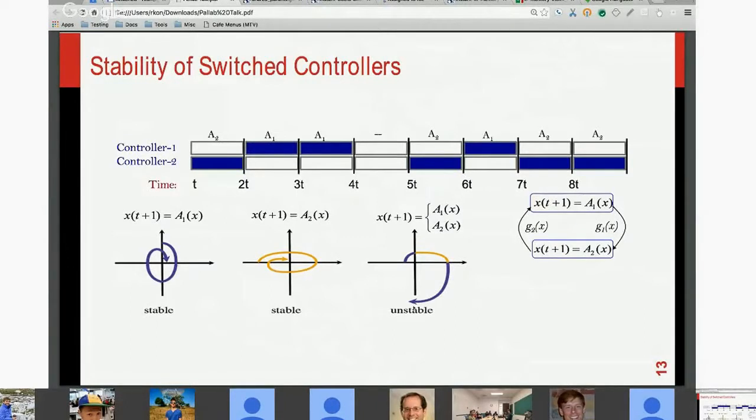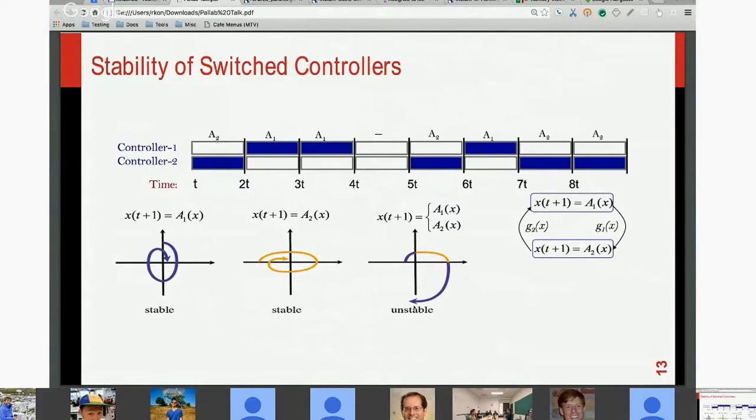There is a nice example which we use when we try to explain what instability of control is. It's a thing that we all encounter every morning when you try to fix the temperature of your shower. If you turn the knob to the left, it becomes cold, and you turn it to the right, it becomes hot. Now, if you keep on turning vigorously to the left and right, you will have instability, because you will get cold, you will not be satisfied, you will get hot, you will not be satisfied, and this is instability. You just flip between two ends. But the real stable controller will be that you gradually bring it to the point which actually gives you the comfort. The important thing to understand there is the